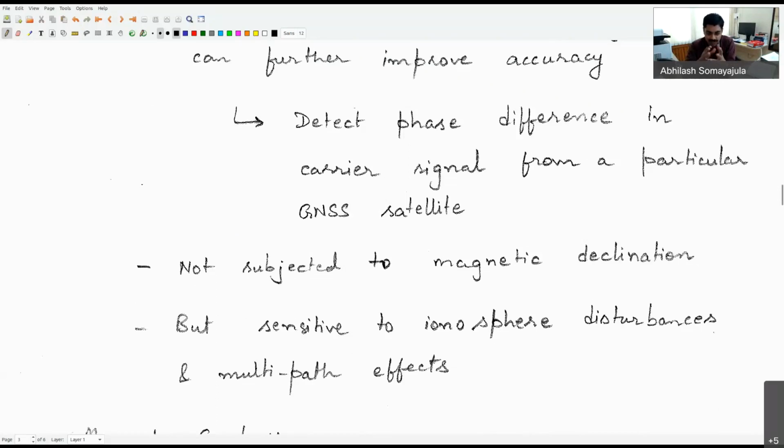Because let's say we are trying to understand based on the Earth's magnetic field, and if I have a strong iron, if my hull is made out of iron, then it's unlikely that my magnetic compass will show me the true north direction effectively. Similarly, if we have BLDC motors or motors which are running and drawing high power, those currents will generate magnetic fields which can interfere with your magnet as well. So therefore your compass may not be as accurate, right?